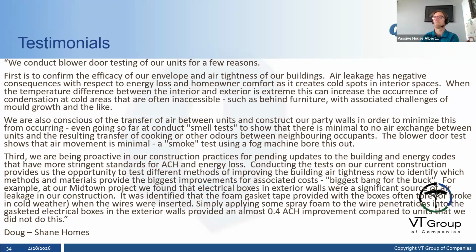Yeah, so you're right. Shane Holmes did touch on that on theirs. Doug is over at the multifamily arm of Shane Holmes. I've worked with Doug a lot on various projects over the last probably 3 to 4 years. The biggest issue with air tightness in terms of attached product is that the air tightness numbers that we have to report on EnerGuide labels do not effectively reflect the overall air tightness of that unit compared to how they would for a single detached house.